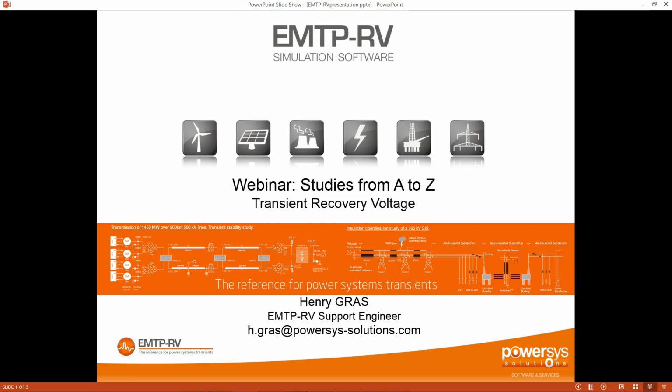voltage across its terminal. The standard IEC 62271-100 gives the rating envelope of the voltage withstand for a circuit breaker above 1000 volts while it is opening. The goal of the engineer is to make sure that the TRV resulting from a breaker opening, so-called inherent TRV, caused by any event that can occur in the network, stays in the rating envelope, also called rating TRV.